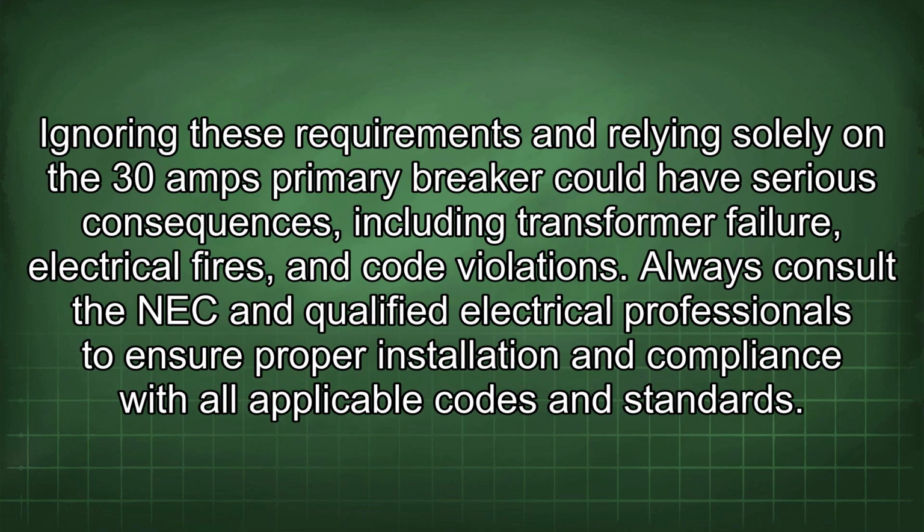Ignoring these requirements and relying solely on the 30 amp primary breaker could have serious consequences, including transformer failure, electrical fires, and code violations. Always consult the NEC and qualified electrical professionals to ensure proper installation and compliance with all applicable codes and standards.